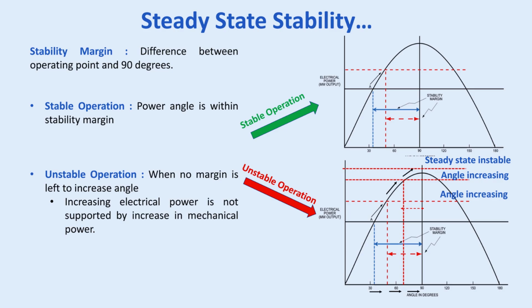The presentation then brings up power transfer limits and these N-1, N-1-1, N-2 criteria. How do those connect to steady-state stability? These are crucial planning standards. N-1 means the grid must remain stable, including steady state, even if any single major component fails unexpectedly, a big line trips, a large generator goes offline. Okay, handle one failure. N-1-1 means handle one failure and then another one happens before you can adjust. N-2 means handle two simultaneous failures.